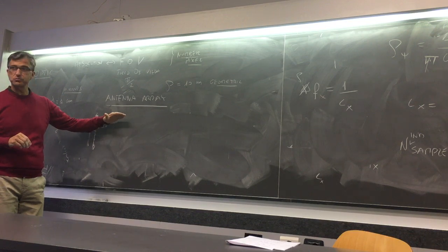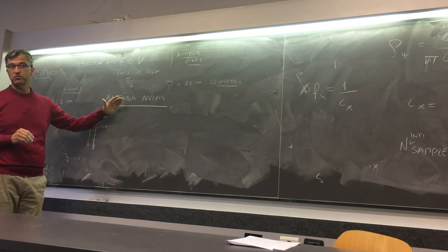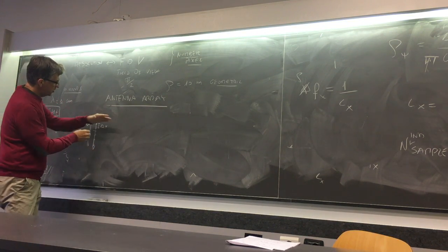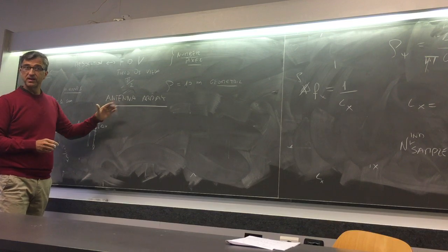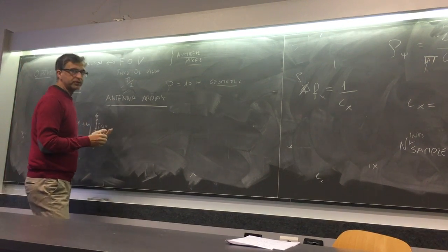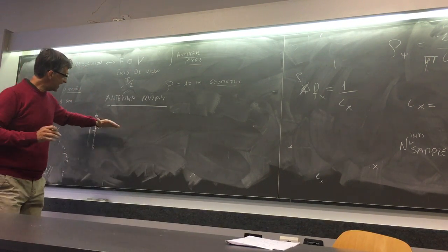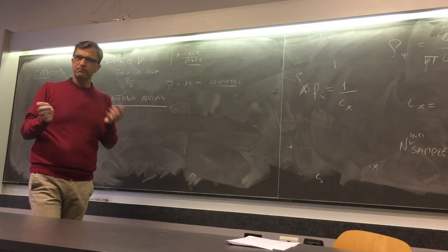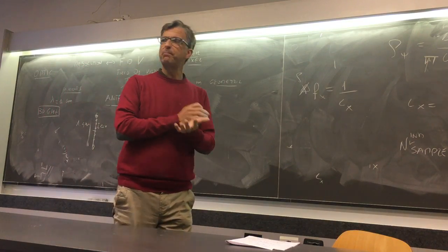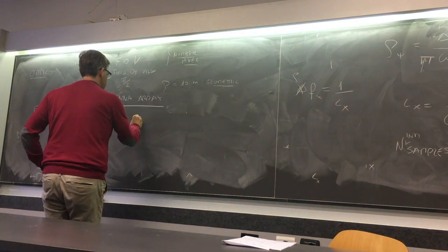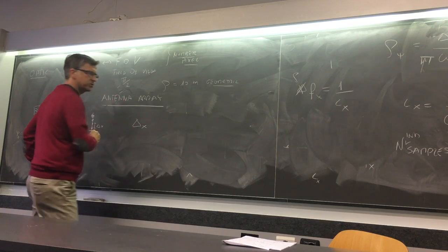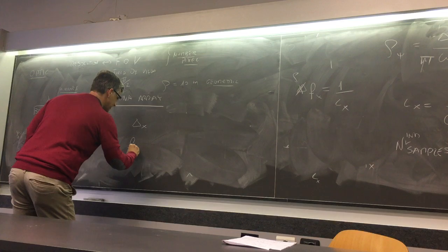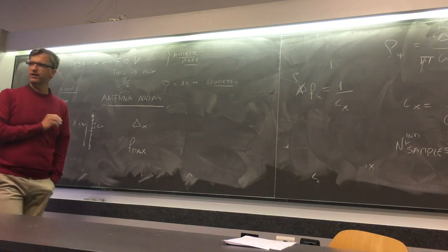each direction corresponded to a frequency, a spatial frequency. So, as for the sampling, each direction is a frequency, okay? So, if you want to correctly observe a sinusoid at a certain frequency, what is the sampling related to the frequency? How much should the sampling be? Suppose that you have a maximum spatial frequency.